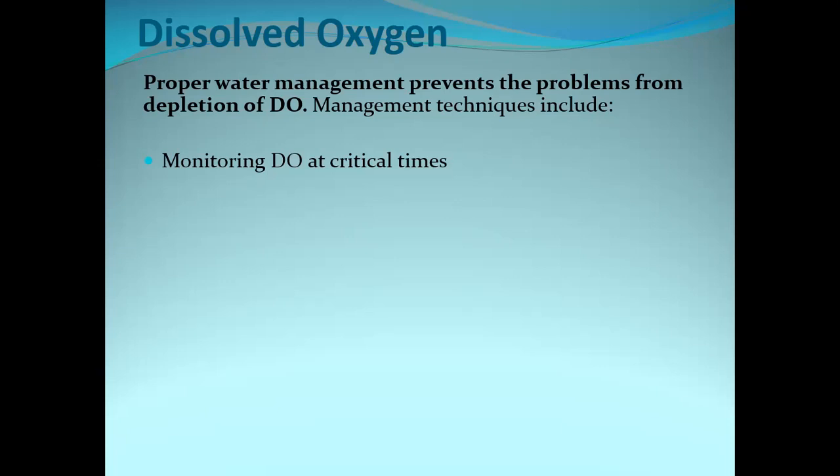In the evening time, you have your highest concentration of dissolved oxygen. Because if you have algae and plankton within your system, you will have the sum total of oxygen produced for the entire day, and it will be at the peak in the evening. So you want to know your maximum and you want to know your minimum. Those are the critical times you can measure your oxygen to have a good feel of what is going on.